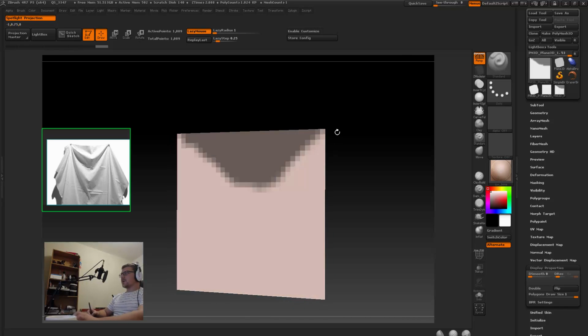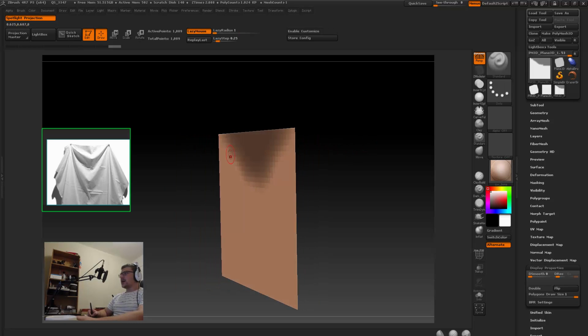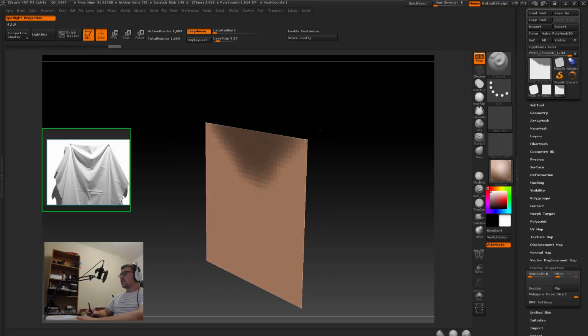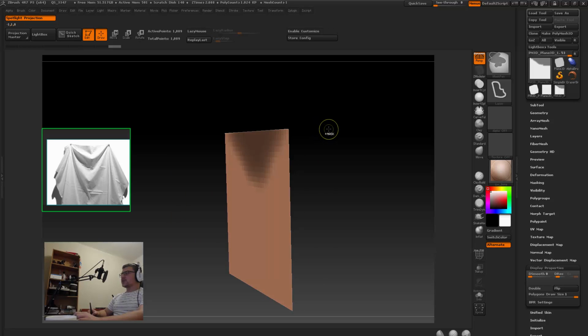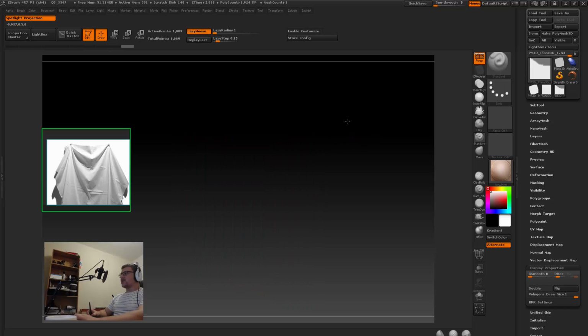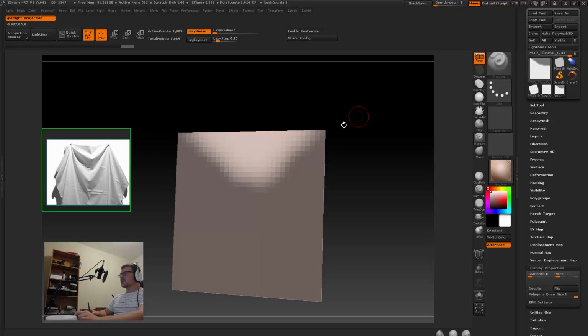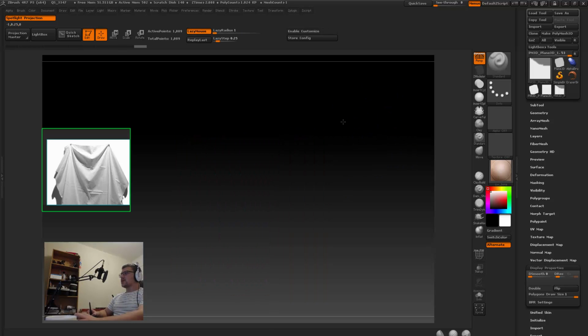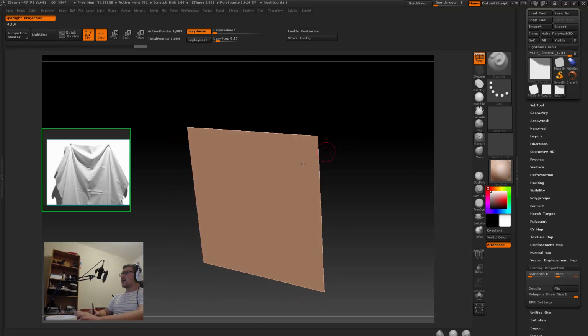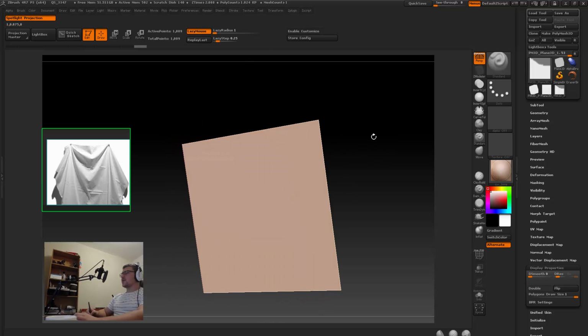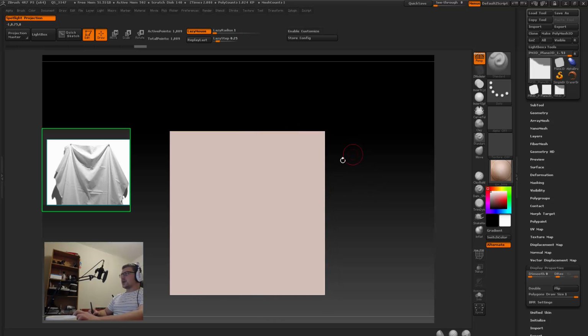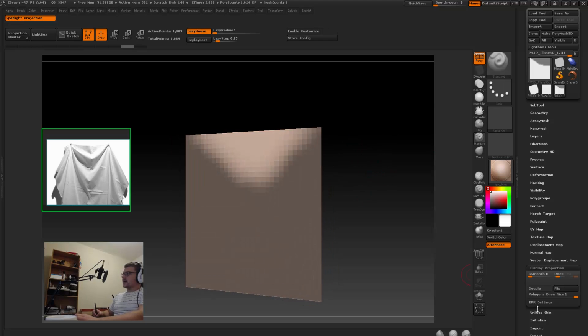And then what I'm going to do is you can hold down control and tap once or twice on the mesh, and that's going to start blurring out the mask for us. I'm also going to reverse the mask by holding down control and tapping outside, and that will just inverse the mask for us. If you want to clear the mask, you can hold down control, click and drag out here, and that will just get you to a clean, clear, unmasked object where we can work from scratch again. So back again, undo that.